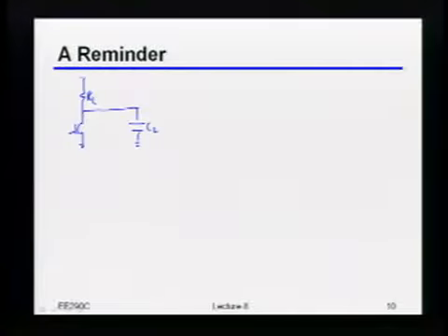Okay? So let's just say I have a standard resistively loaded differential amplifier, and this thing is driving some explicit load capacitance. But let's not forget that any transistor I put there will have its own self-loading capacitance. Okay, so first question: let's assume I knew what the total capacitance was. What sets the required GM?